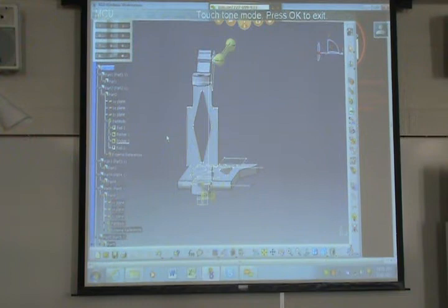And so as you're able to make these changes inside top down, there might be a part that you realize is created incorrectly. You could go in and change it. And if this thing is set up appropriately, it should automatically update all of the parts that are associated with that constraint. So that's why top-down is really cool. It allows you to make those changes without having to reconstrain all of the parts. Its disadvantage is it sometimes does take time to set up a top-down assembly, but it pays off in the end because you don't have to worry about changing all the individual parts one at a time.